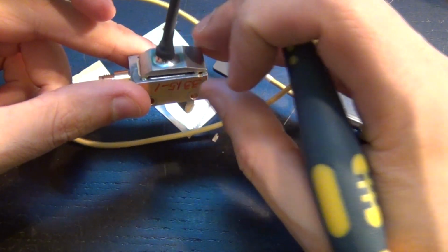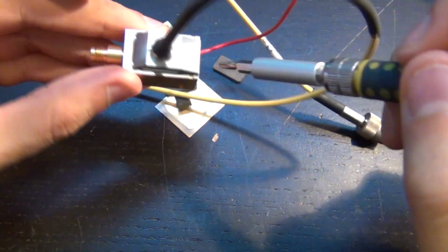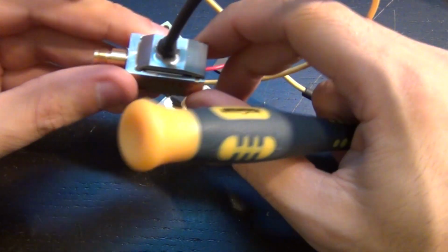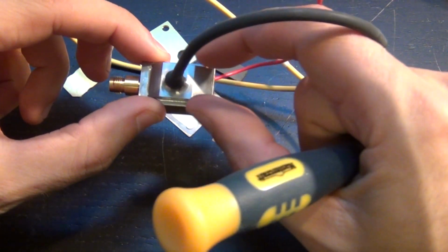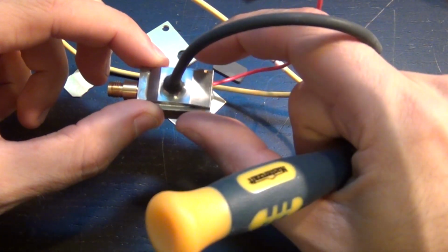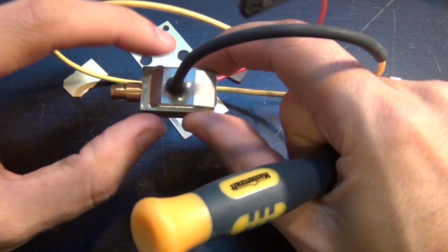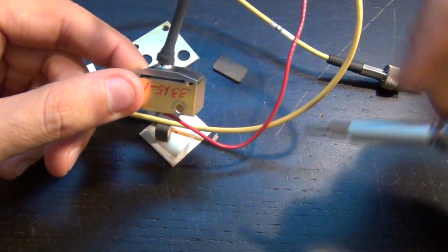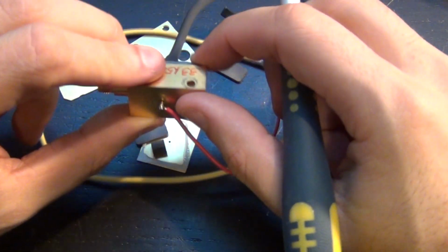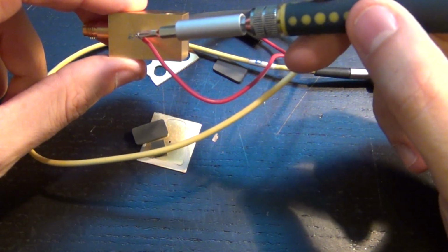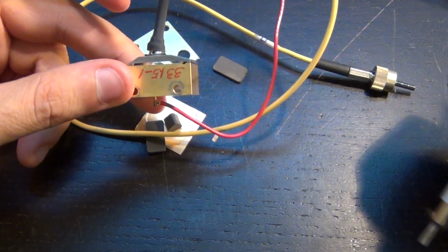Obviously, again, totally customized for this purpose, but I am curious about snapping this off. The alignment of this is done in the lab. So they would put this in, put the light in there, connect this to a signal, align this with the machine very carefully, and then they weld it or glue it in place, because if you align it even by a fraction of a millimeter, then your responsivity goes down the drain. So this is why it's so important that this is done this way. This is custom, so they don't really care about the cost of testing and alignment. And here is the biasing for the photodetector from a single pin going into the chassis, of course, the other terminal.